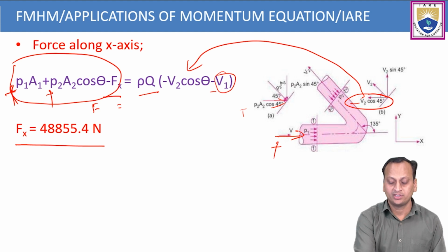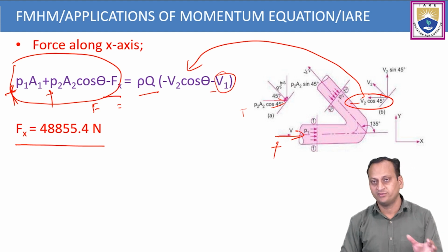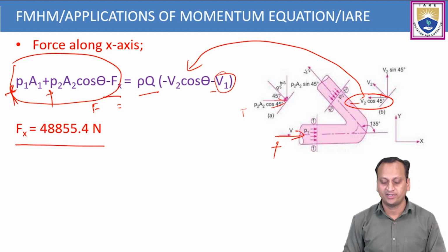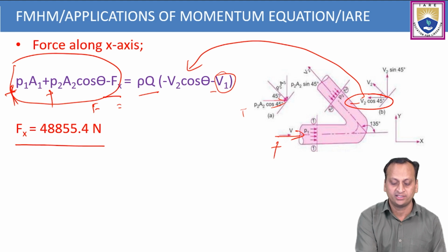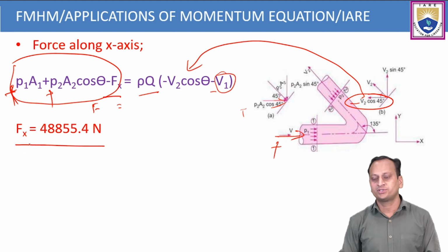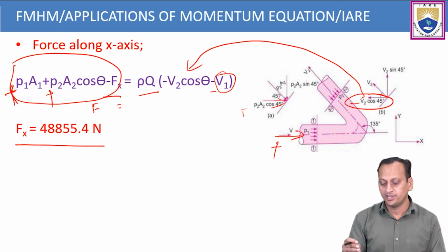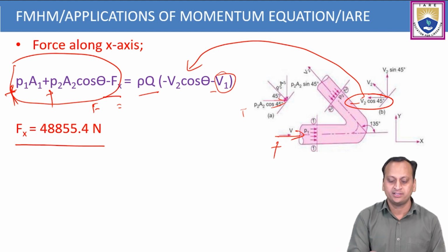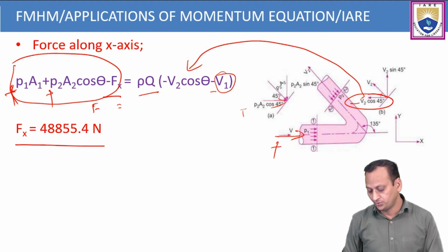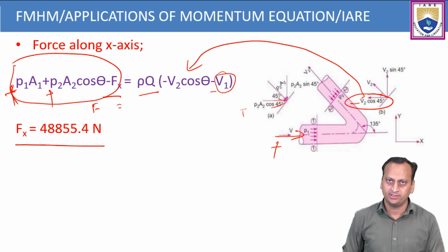If you substitute all the given parameters, the pressure, velocity, area, these are all provided. You need not apply Bernoulli's equation here to calculate unknown parameters. All parameters are given. You only have to calculate the force about x by applying the suitable expression. After drawing the diagram for the given orientation, the resultant force about x can be derived.